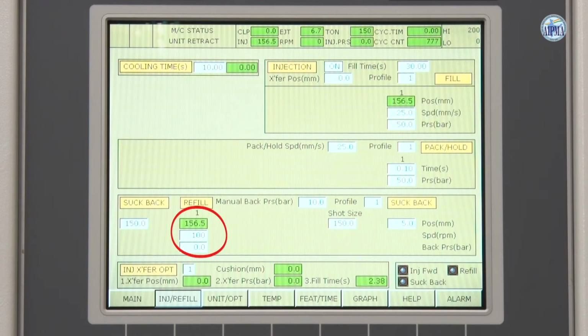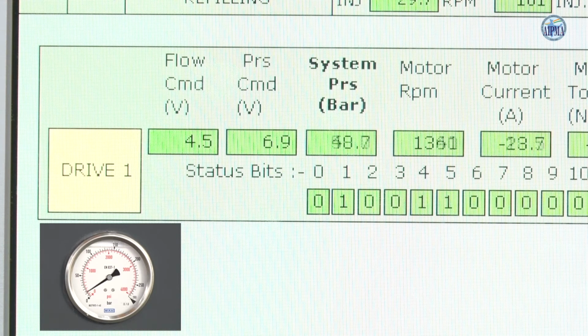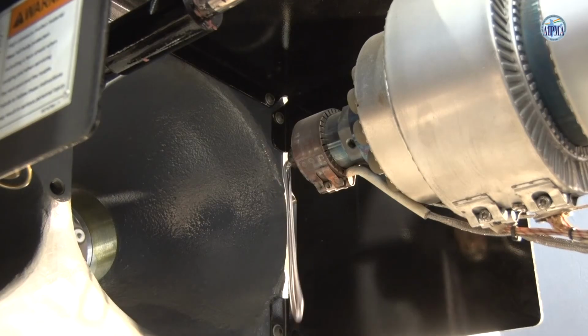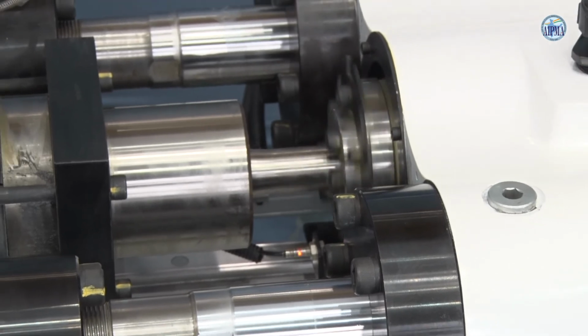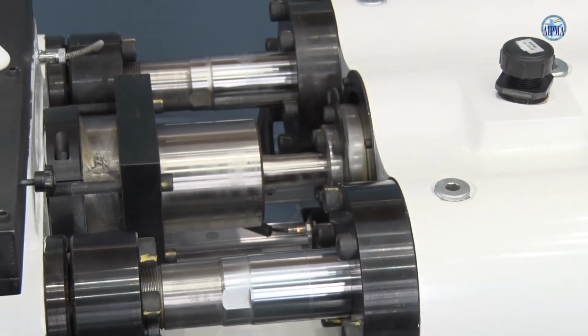Initial screw speed should not exceed 15 to 20 rpm so as not to damage the screw or barrel. During this time, when the screw is recharging, no one should be standing near nozzle. As the screw starts to refill, the motor load will gradually increase. This is an indication that material is feeding. Once a steady flow of polymer exits from the nozzle, the screw speed can be increased to the desired operating RPM. Machine is ready for operation.